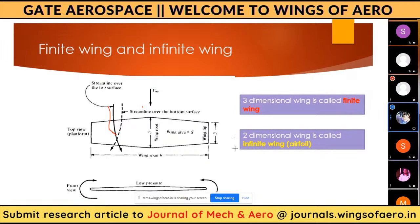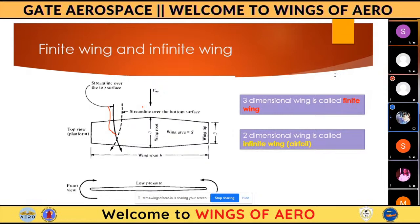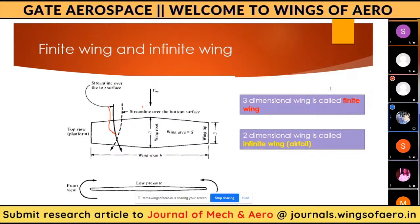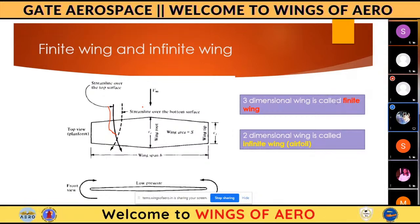If it connects from one end of the window to another end of the window in the test section, or one end of the mirror to another, then it will act as an infinite wing, not a finite wing. The finite wing means it will have some definite length. So aircraft wings act as finite wings, but aerofoils act as infinite wings. That's the main difference.